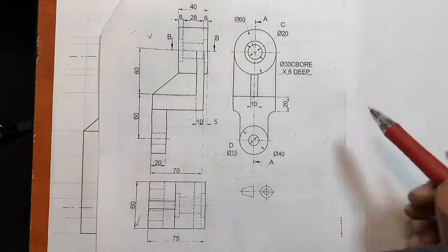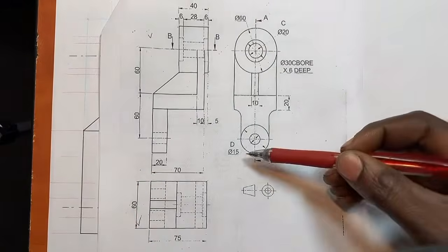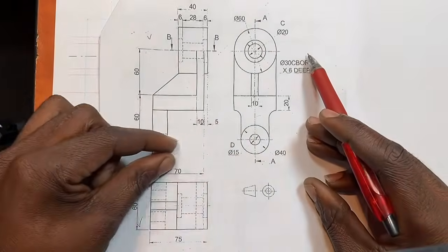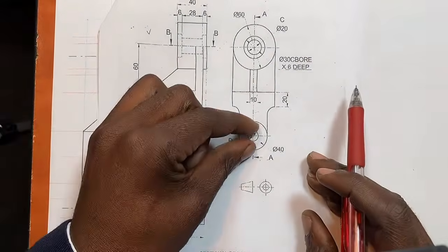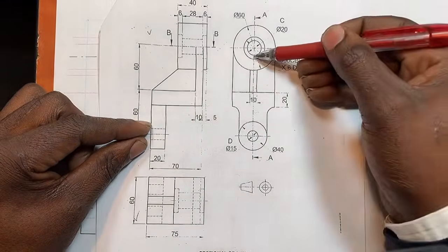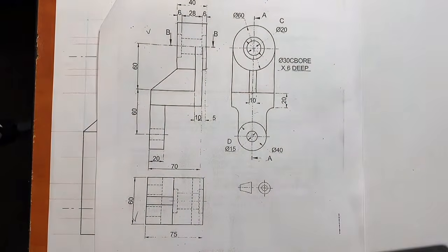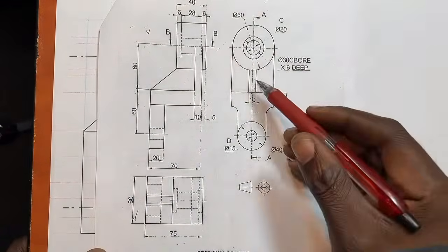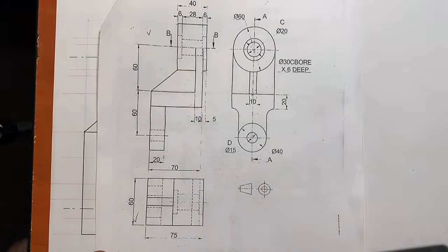You understand? So in other ways, the hacksaw cut it from here till here. So when you trace this gap from here till here, it's supposed to be in sectioning. From here till here, it didn't cut. When you trace this gap again, it's not supposed to be in sectioning. So from here till right there, when you trace this gap, you must be having hatches, you understand? So you must have a strong point to rely on. Another point, we do not cut a supporter when it's cut along its height or along its length. Should it be cut across its height or across its length, that's when you're going to section.